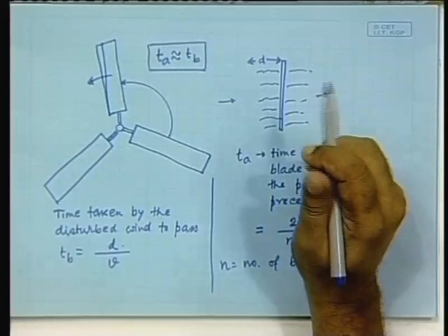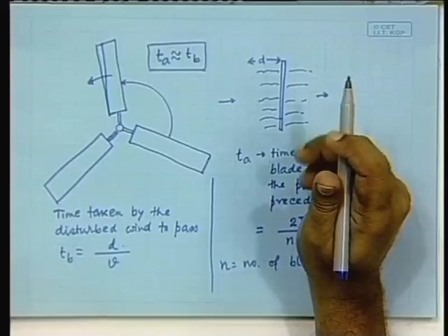For example, normally 2 or 3 blades you will find actually. So, it is a question of a choice, different companies choose 2 blades, different companies choose 3 blades. The choice is dictated by the fact that if you have 2 blades, obviously you will produce some less energy, because as you have seen while we were calculating, we multiply by the number of blades, but not much.